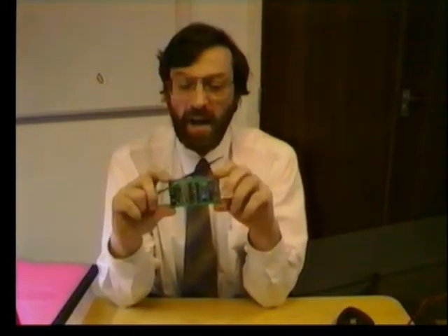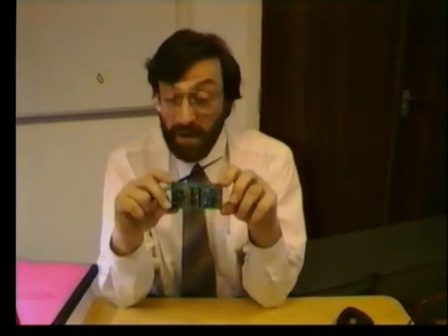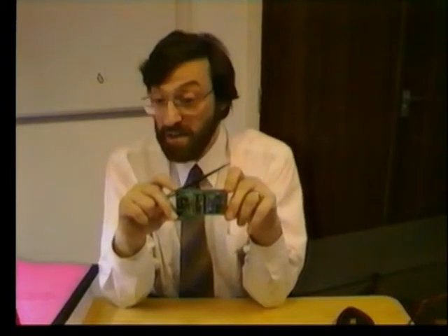Everything I've shown you up to now has been something that controls something else, but this is quite an interesting little beast. This is an embedded system. It's an infrared thermometer. It reads in the light output in the infrared spectrum from a source, a body, by viewing it with an optical sensor, and basic science tells us that the spectrum of infrared is directly related to the temperature of the body. So you can use this for remotely sensing the temperature of extremely hot bodies. Up to about 1300, 1400 degrees Celsius this will operate.